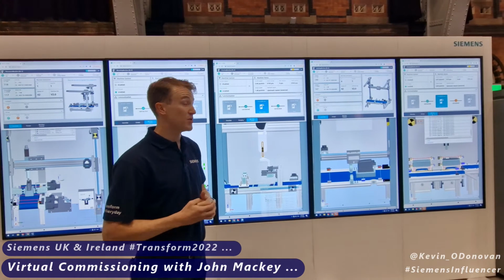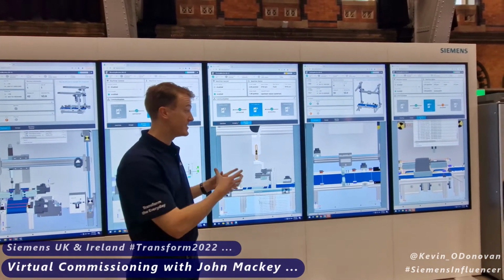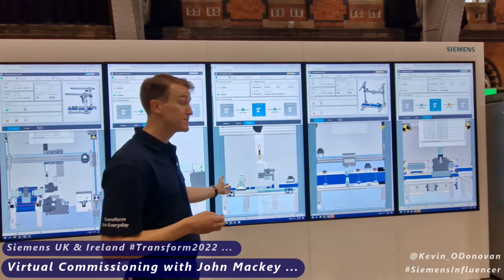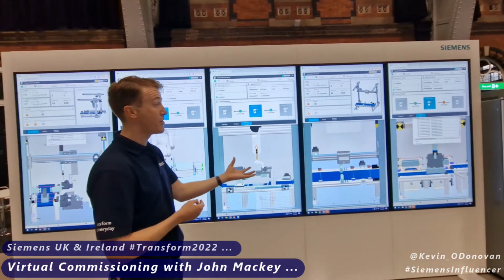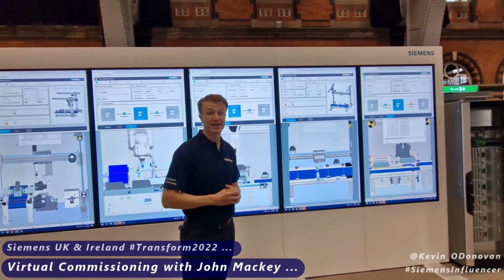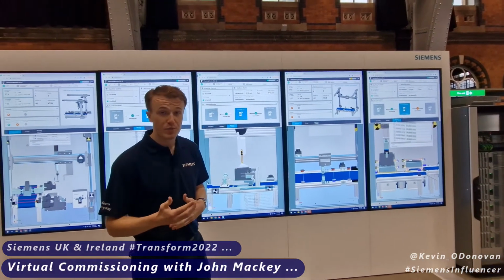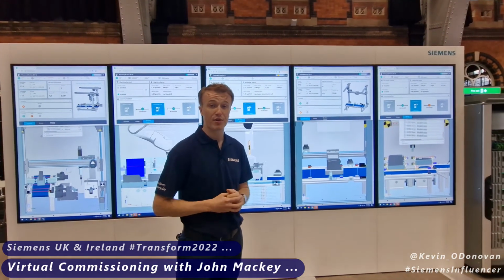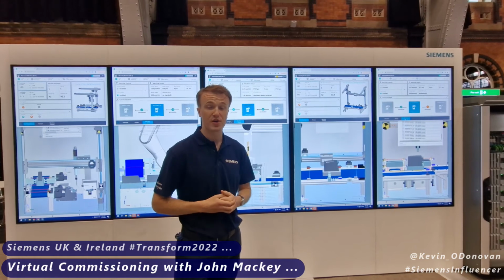The final part of this is once we have the digital twin, and then this is in production, we can then run scenarios. So for example, what happens if we speed up the conveyor? Does that make our production increase by 10%, or does it actually create a bottleneck during the end? So all these scenarios can then be run, which then feeds back into the process and can improve that quality, improve that product. And for us at Siemens, that's what we call virtual commission.